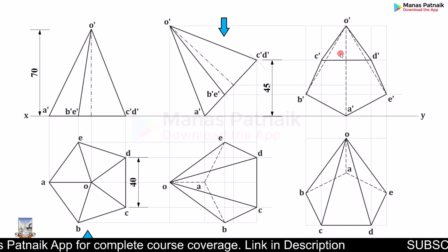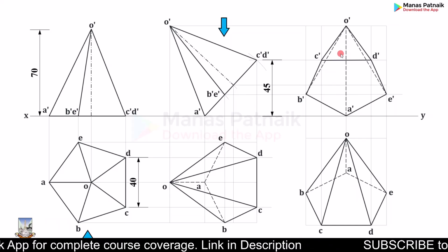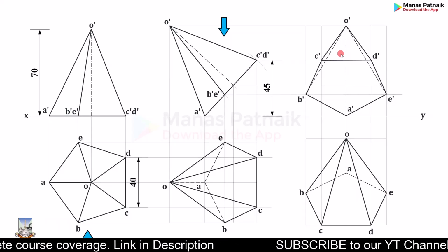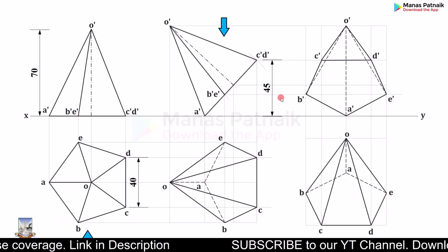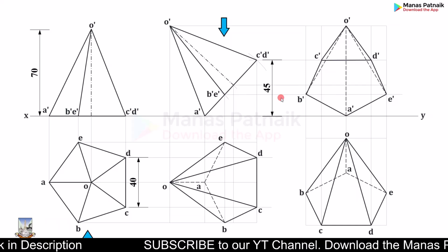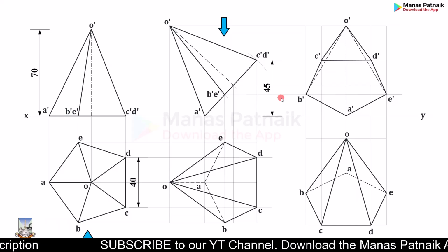Anyway, so that was the solution. And as far as the construction work is concerned, please make sure that the projector lines stay very, very light. Use a 3H or a 4H pencil, right? This is how the final solution looks. Thank you.